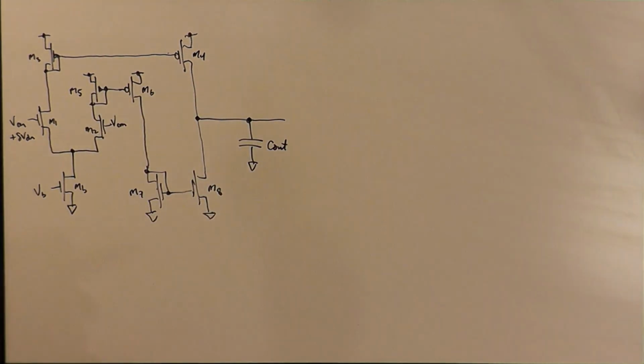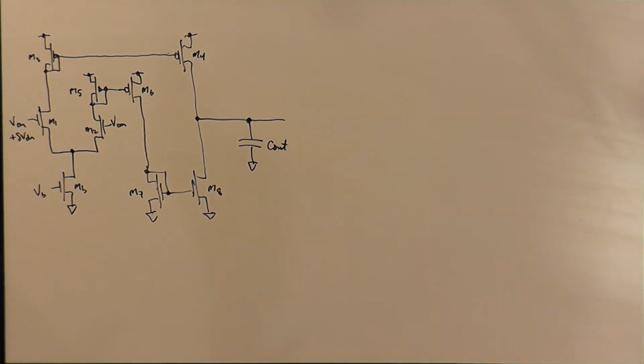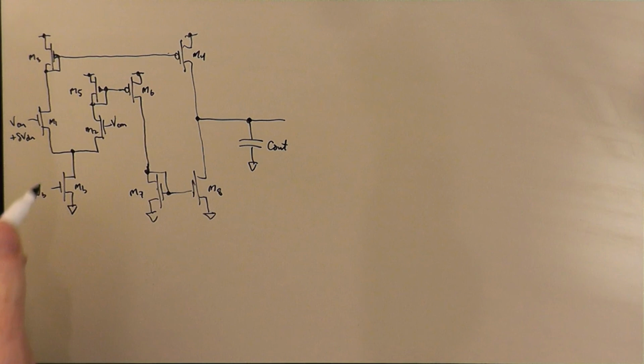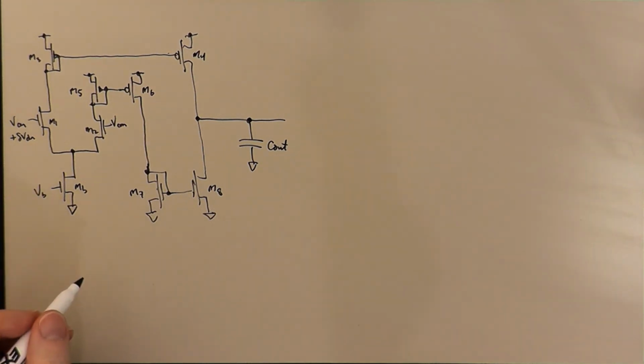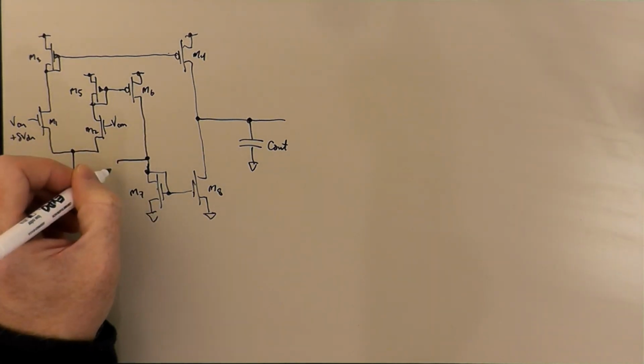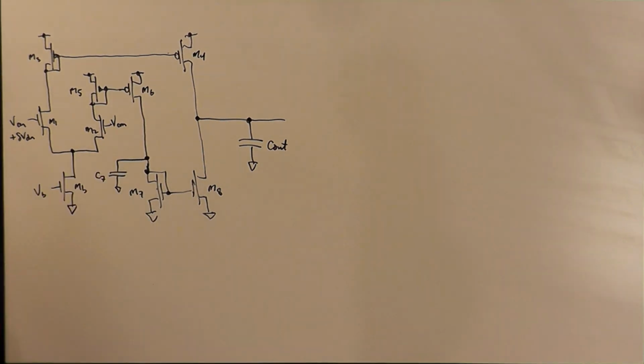And so the question is, why not consider some sort of internal capacitance in here? Why just put in an output capacitor on here? And what I'd like to do to try to get an intuition for what's going on with these other capacitances is to, let's suppose we were to put a capacitor here on this node, call this C7. This is not an explicit capacitor we would actually put in the circuit here.